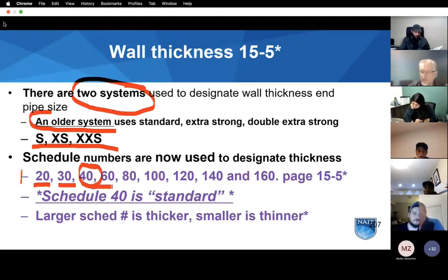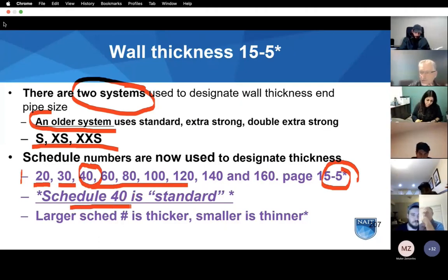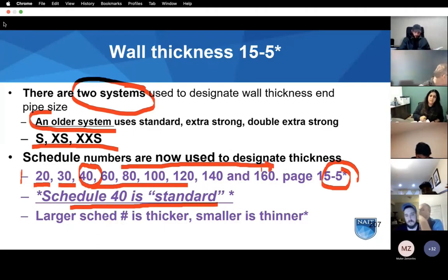When we get into some serious pressure in our piping, we're going to be using schedules like this. Okay, this is all from the pipe charts in your textbook. So schedule 40 is standard pipe. As we go from 10 across the chart at the top over to something like 160, it looks like double extra strong is even thicker than 160, by about double, just scanning the numbers of thicknesses there.